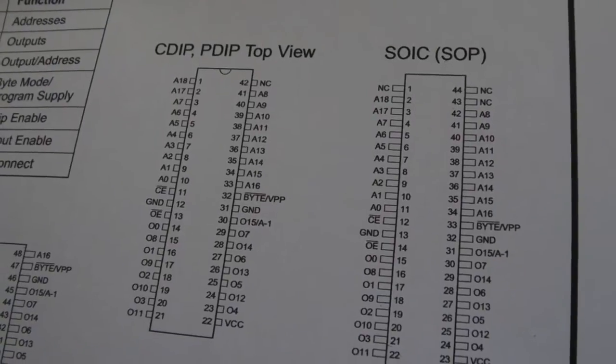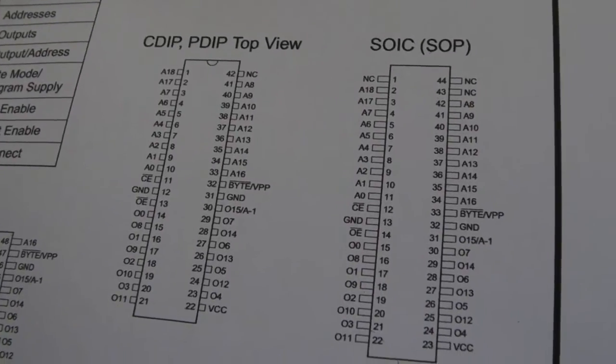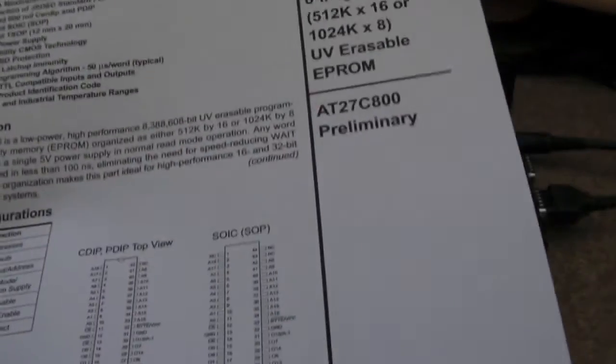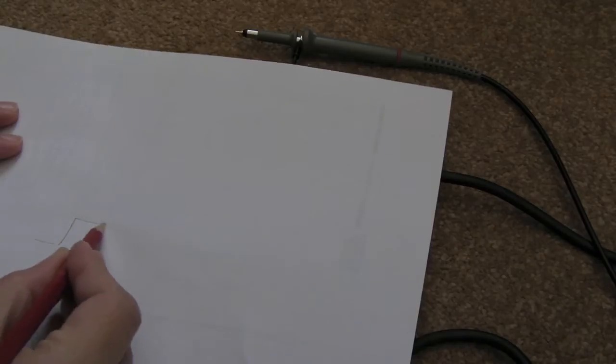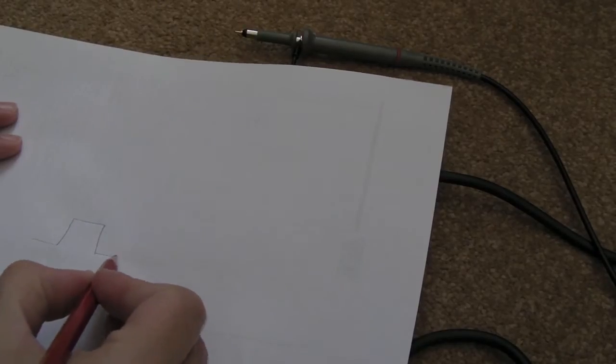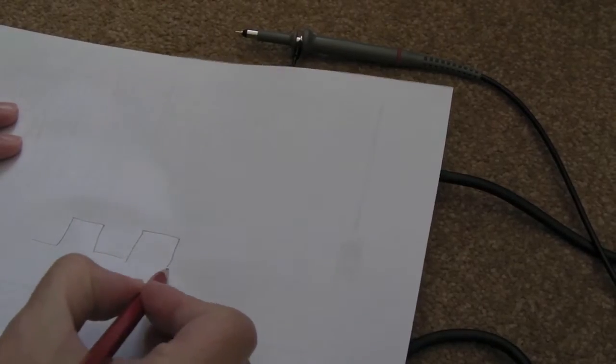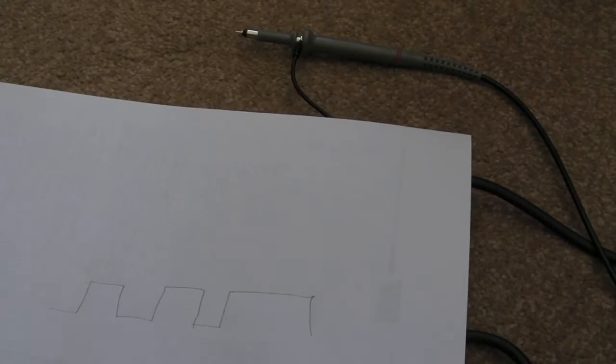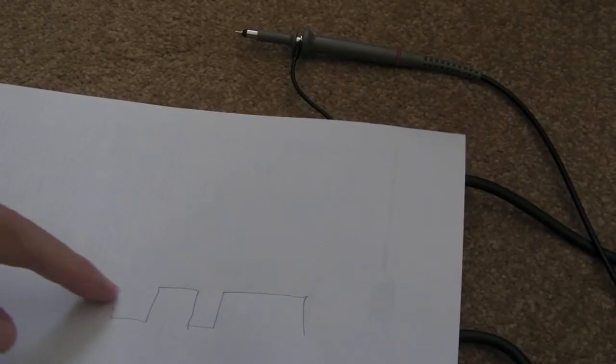What I'm expecting is we're probably not going to get a normal TTL level there. Typically, I'll try and draw this, what you expect is rising leading edges fairly square like that, where you've got your logic highs.